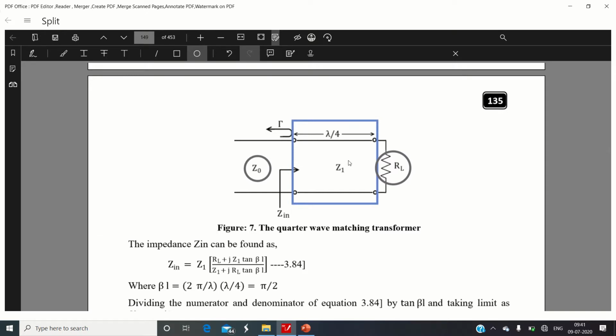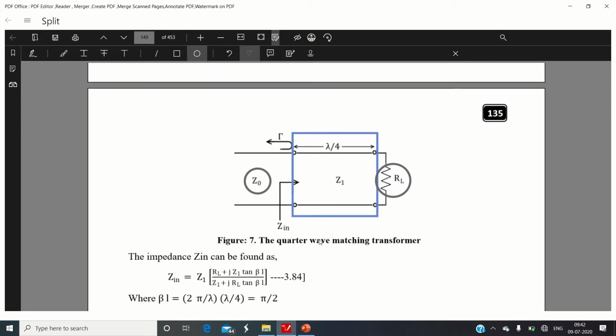But there could be a standing wave ratio on the quarter wave transformer itself. So we are suppressing the reflected wave at the generator side. Later in this lecture, we will see a brief tutorial on voltage standing wave ratio and the reflection coefficient. So let us go further.